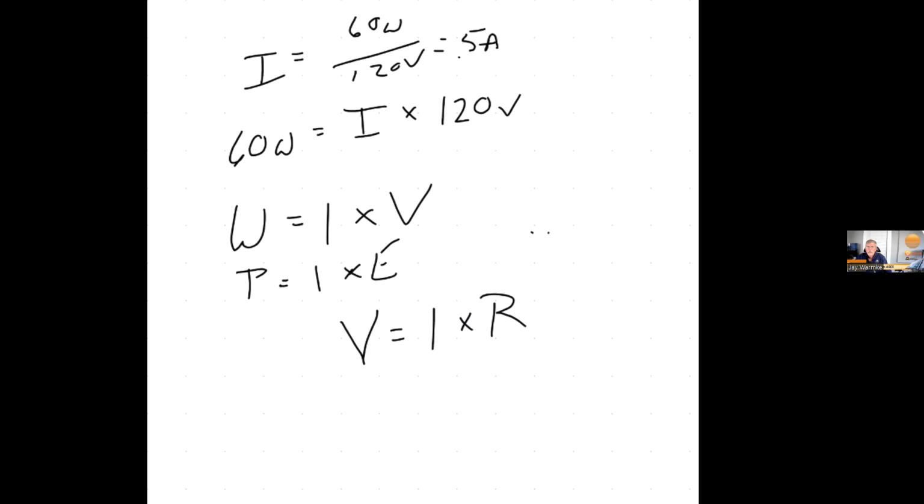All right, I'll write up here in this corner. So voltage drop equals amps times resistance times twice the distance divided by 1,000 feet. So that is a variation of Ohm's law. So why are we making this variation?